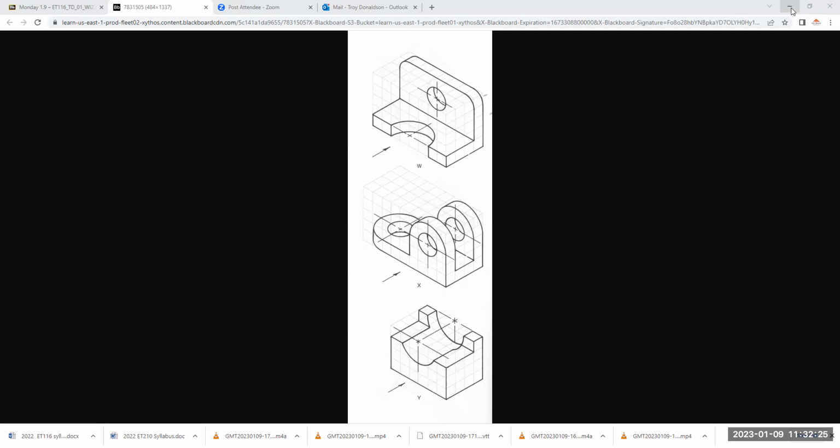Yeah. So under text, so we're in dimensioning, right? Under text is the text height. 0.125, that's 1/8 inch. That's going to be what's on the paper. Okay. So you have to think about, like, if it's a really big drawing, it's going to get shrunk down to the paper.